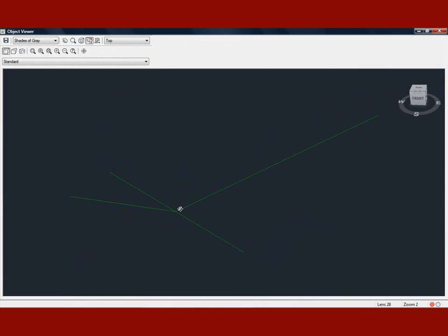Because this line was here first, it was at 700. When I superseded that at the 680, because they're in the same site, it has to take two feature lines that are crossing in the same site, cannot have but one elevation. So they can't cross with two different elevations. That's the entire issue. If you want this to happen, that's a great tool. If you don't want this to happen, it's not such a great tool.